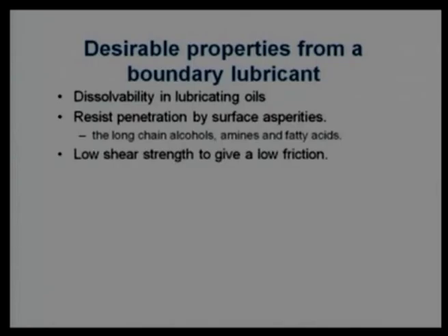Above all, as we discussed in the friction lectures, we need to have low shear strength of the interface. If the interface does not have a low shear strength, the whole of tribology comes to zero, it does not have any use. We need to make the interface have low shear strength, and that is a necessary condition for using any lubricant.